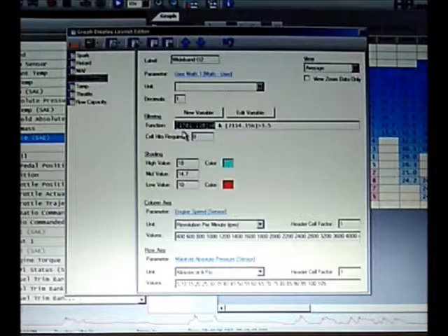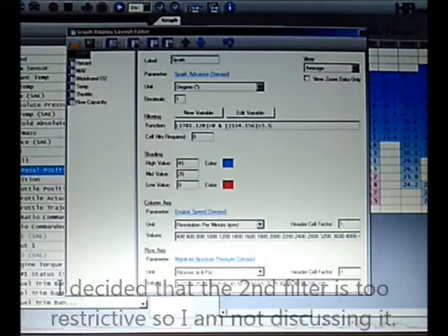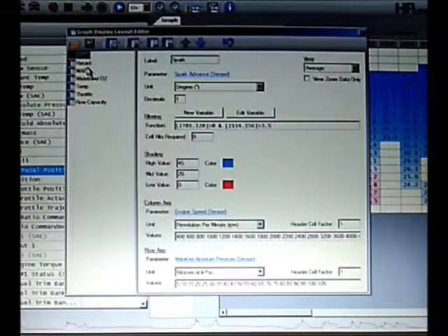The first one, PID 2701.120, greater than 0. That means that the torque on the engine, or the power that the engine is making, has to be greater than 0. If the torque that the engine is making is negative, it means that it's decelerating. So I made that greater than 0 as one condition. I applied it to spark because I don't want to pick up any spark values that are part of the decel range.